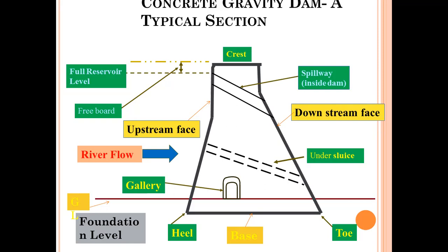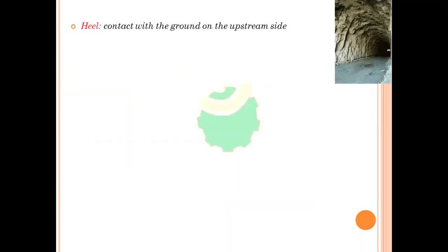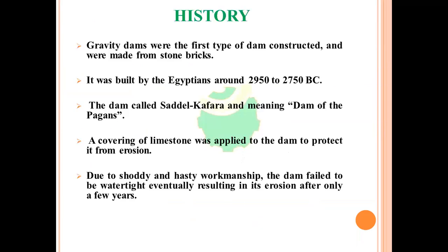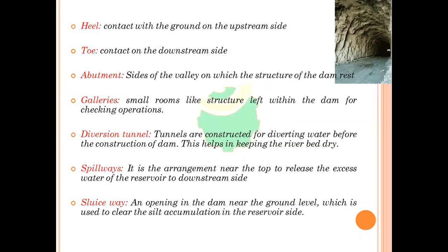So that's why in designing of gravity dams, we must concentrate on full reservoir and empty conditions, and the forces in two cases at heel and toe. Those calculations are very, very important. Next, heel, contact with the ground on the upstream side. Toe, contact on the downstream side.